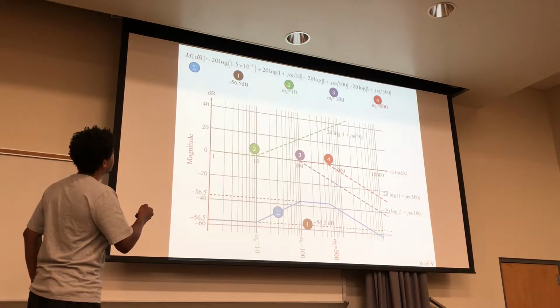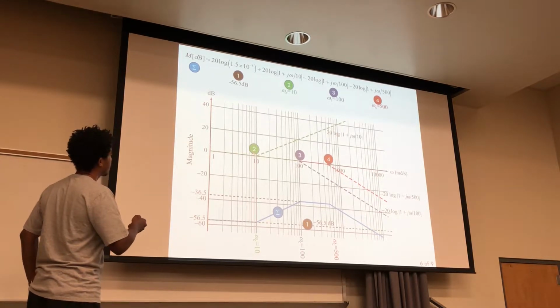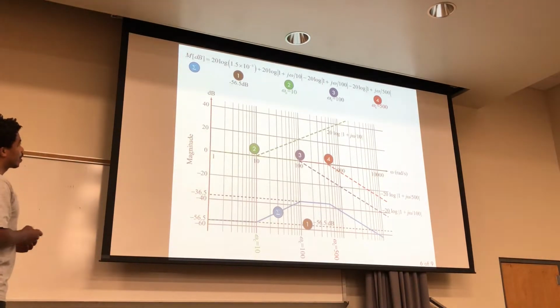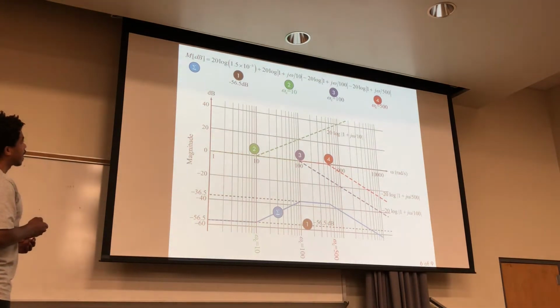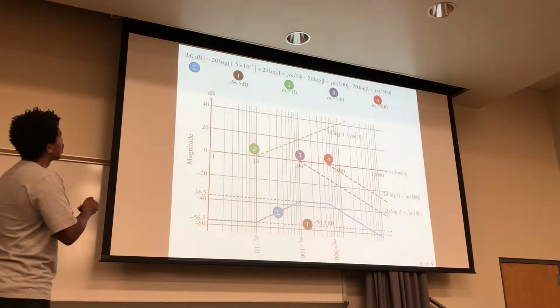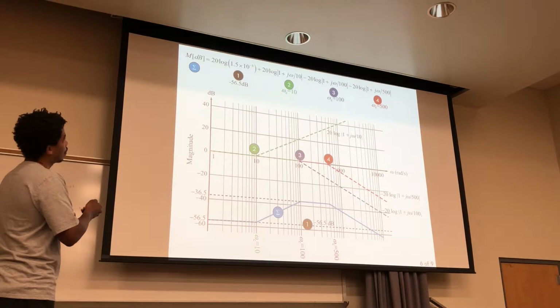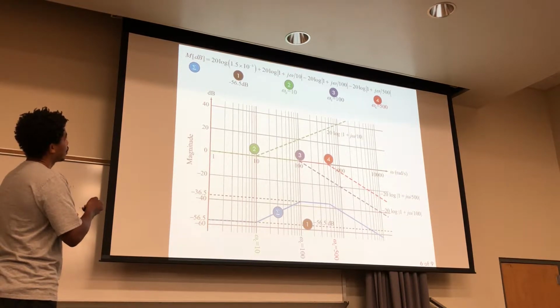And if you were to plot this out, is this part right here. I'll try to explain that. So what's going on with this part is that at the cutoff frequency of 10, right here, you have a magnitude of square root of 2.